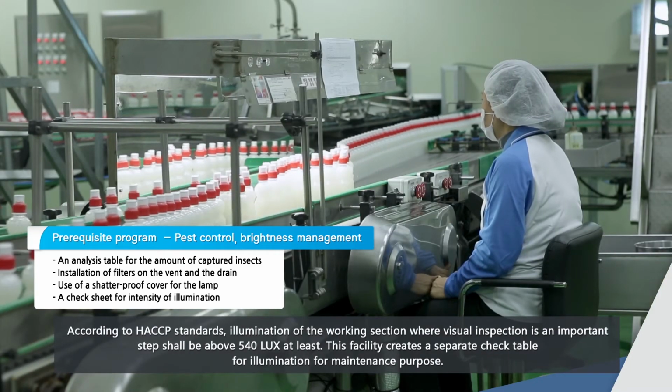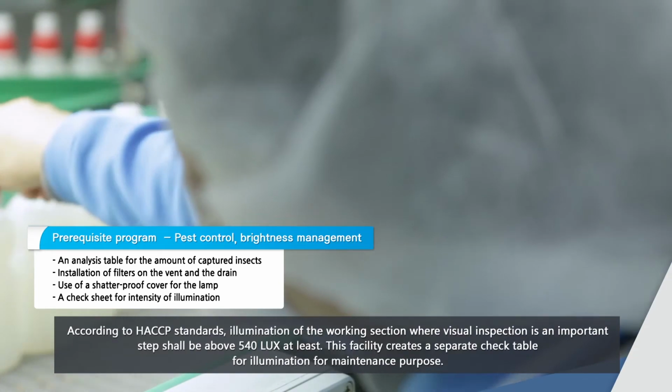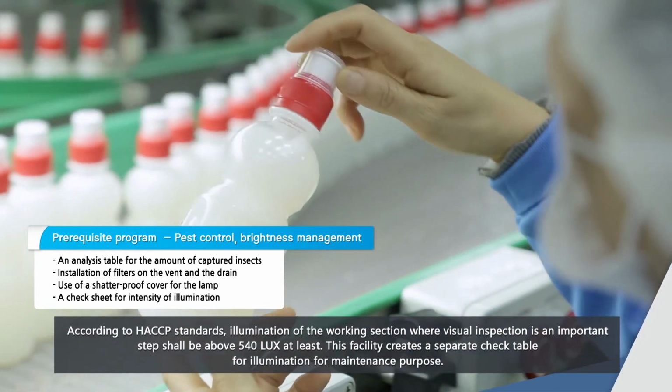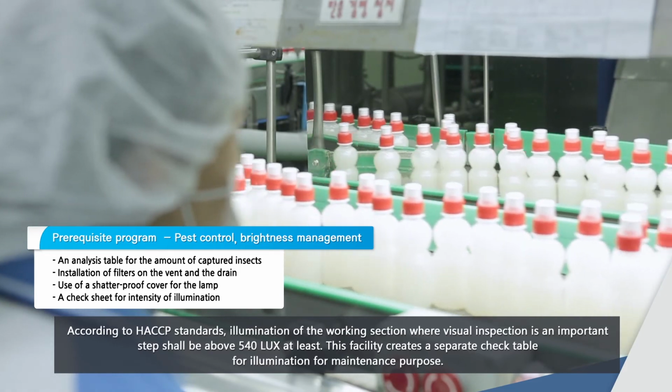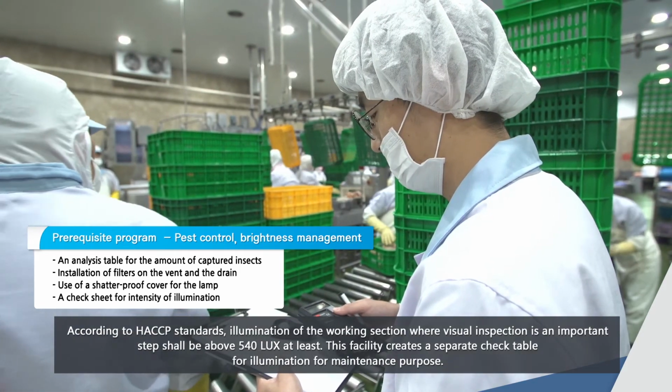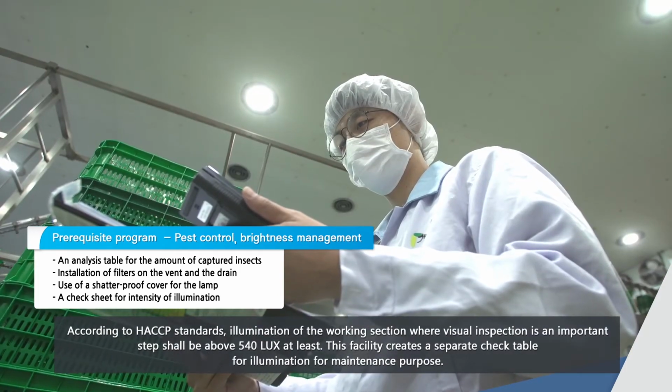According to HACCP standards, illumination of the working section where visual inspection is an important step shall be at least 540 lux. This facility creates a separate check table for illumination for maintenance purposes.